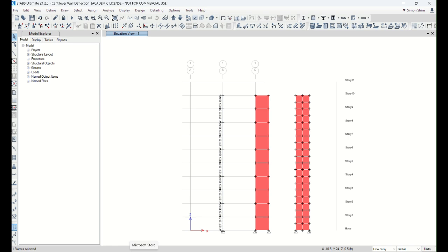Bending moment diagram. Simple. This is a cantilever. P times height, right? That's the bending moment at the base, right? I'm just giving you the heads up. I'm using a small model because what you learn or formula should be fully reflected on this 3D model, right? But in a slightly different way depending on how you model.